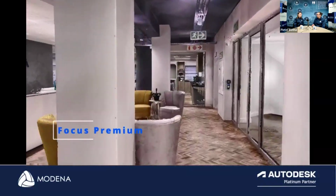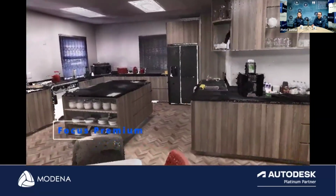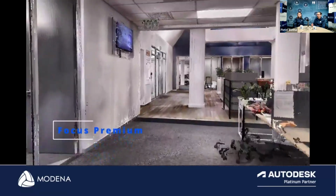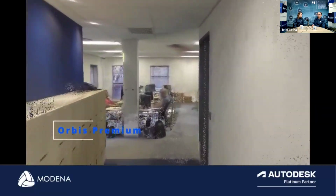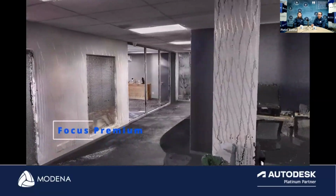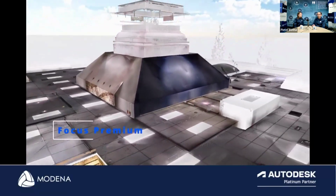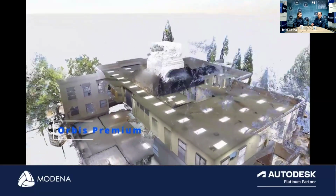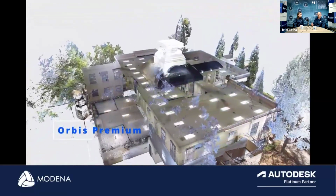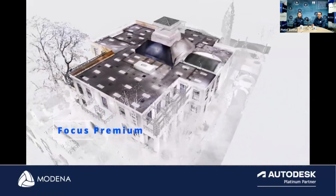Some might be wondering where the Orbis will work and where the Focus will work. As you can see in the video plan here, the Focus provides us with more detail than the Orbis scanner. The Orbis scanner provides us with positional information. We can go into detail on certain objects by using the flash scan. But the majority of the use of the Orbis would be to capture large data, large sites, very quickly. And then we can always go back with the Focus scanner and add more information that is required in certain areas of the plant, for example.